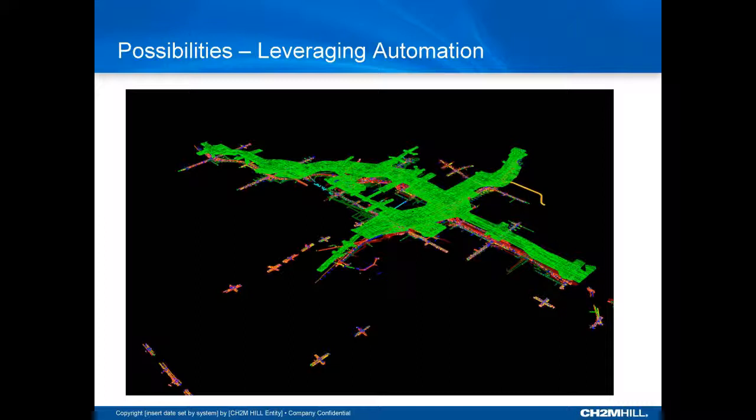Now, in coordination with the utility manager for the project, he had a whole table of assumptions that he used in order to communicate approximate depths per utility type. So a custom application was developed to take the recipe of the 2D data and, by level and by cell, essentially remap the 2D data and drape it onto a 3D file.